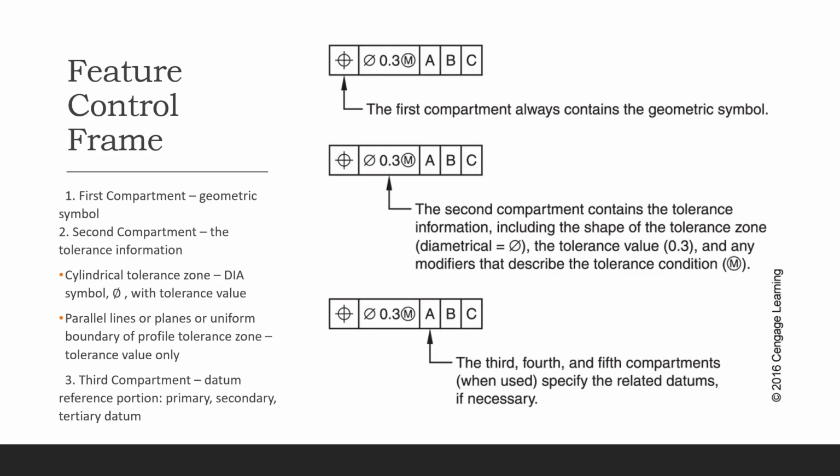Another one is you have to know the frame. We know the control, and the control comes with symbols. There are 5 types of control, depending on the geometry of your measurement. And there is the tolerance. Your measurement has to be within these tolerances, and you will obey. These symbols are telling you where to start, from which reference, from which datum, and whether you have to be careful with the material condition.